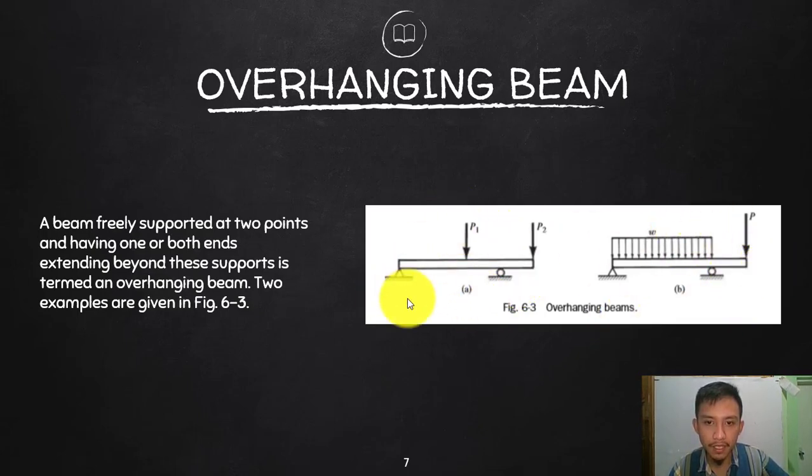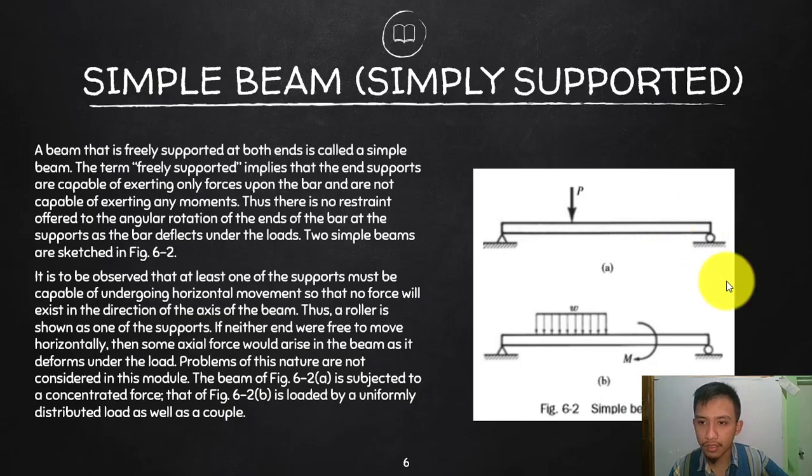But what do we expect here? Since those are simple supports, you will only have vertical reactions, and again there is no horizontal unless you have horizontal forces. But in case you want to cut the beam at the point where the roller is supporting your beam, then you can expose an internal moment, and that is the same as calculating the moment support in your cantilever.